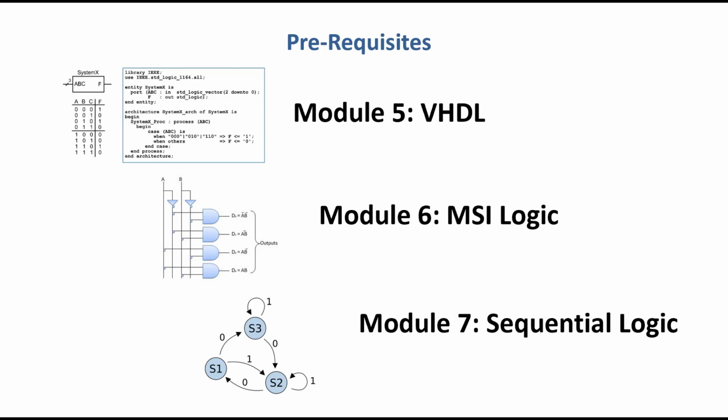And in the prior class that feeds into this class, we looked at VHDL as the primary mechanism to design these digital systems. VHDL is a language, and it gives us the ability to describe a logic circuit in a language. So we actually type out the functionality of the circuit, including the inputs and the outputs, and how the logic is going to operate. And it was very powerful because it gave us the ability to simulate the result and make sure that the circuit is described properly before we actually build the circuit.